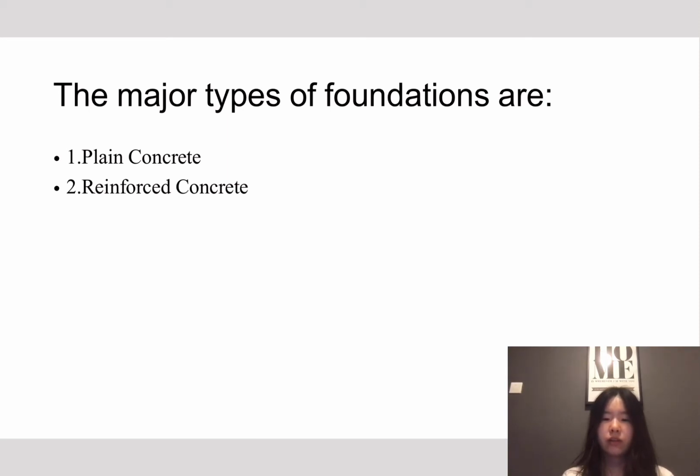Among the commonly used materials, bricks, stones, and concrete are all rigid materials. Flexible foundations use the tensile, compression, bending, and shearing resistance of reinforced concrete material to make the foundation. It is used for buildings with poor foundation bearing capacity, large upper load, a basement, and deep foundation burial depths.